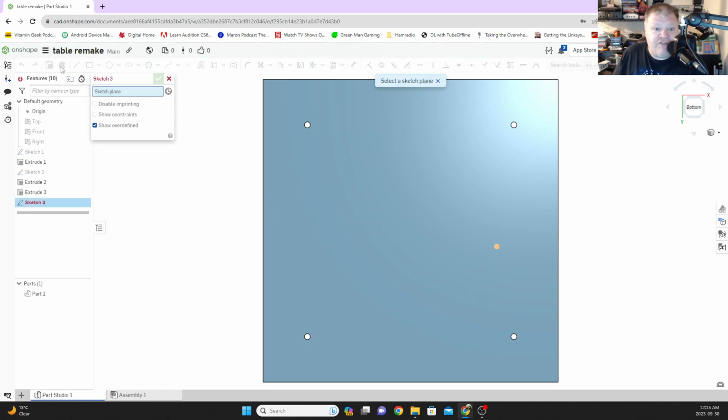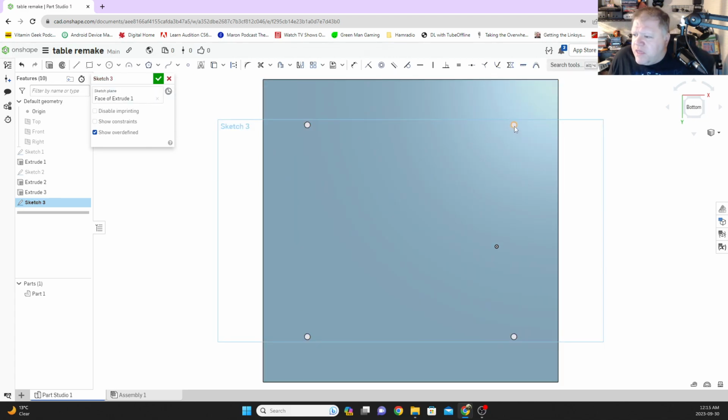First I'm going to click on sketch. Okay. So we have on a plane, here we go. We have these circles that are here and here and here. Now I know that the ones I'm going to be using are ball top style screws. So I want them to sink down a little bit. I know that the length of it is about 2 millimeters, but I want there to be a little bit more depth of sinking because at the very top, it works out to 2.75 if I remember correctly. So I'm going to sink these to about 3 millimeters. And I know the size is going to be 8 millimeters across for the actual button hole.